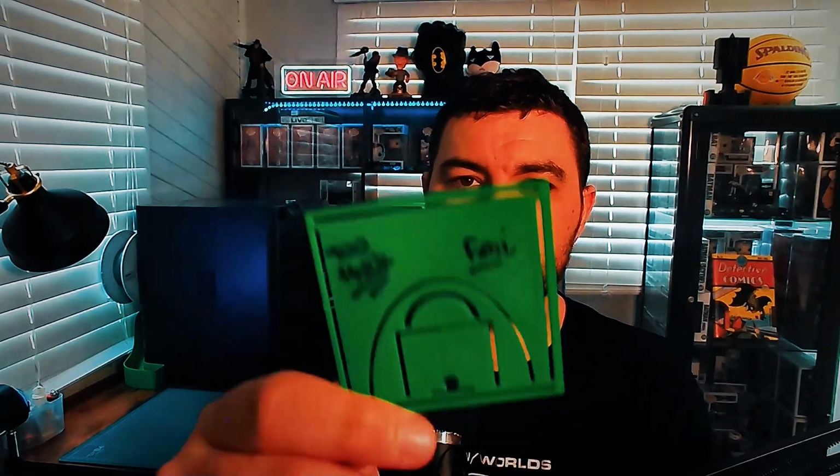This one here was the first one that I did, and overall it looks okay, but the actual lines were way too thin to get the pen in, and also I wasn't happy with how flexible and how much movement was happening with this. I realized that I needed to put more pillars in these top corners. I amended the file and then tried 2mm, but 2mm was way too thick. Like, this is actually way more rigid, which is good, but it was still too high now to get the pen in, even with thicker lines. This right here is the final outcome, and dude, it's perfect.